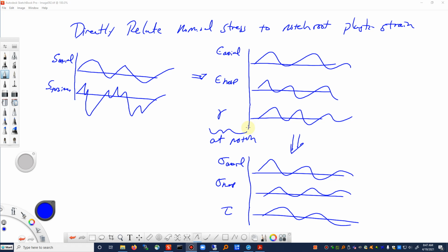It's the fact that the stress concentration factor works together with a nominal stress to produce the elastic notch stress. So in fact, we don't have to use a definition of a nominal stress. We can use our nominal stress as the actual elastic or pseudostress at the notch.